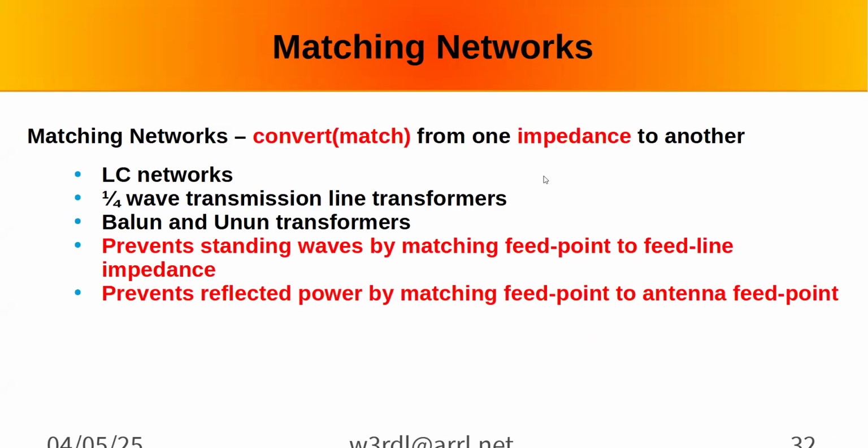I think the point there is you've got a bad match and you tune it to 1-to-1, it's still a bad 5-to-1 match. Doesn't fix anything. Right. Well, it makes the transmitter happy, but it didn't fix the antenna or feed line. And if they'd asked what it was on the input to the matching network, then it was 1-to-1. But they said the feed line.